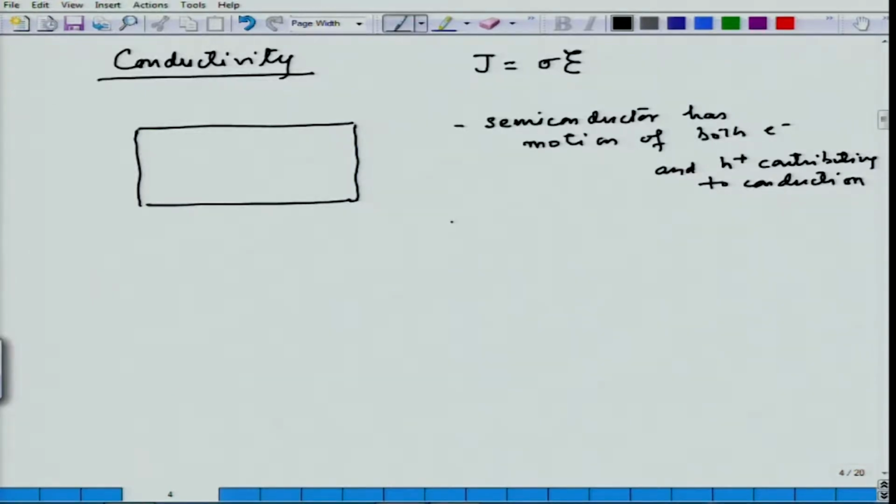And I am going to treat these electrons and holes as classical particles, as we did earlier. The only difference being the electron mass in the conduction band is going to be the effective mass of electrons in the conduction band, and the hole mass is going to be the effective mass of holes in the valence band. So, this is what I have taken from my quantum mechanical picture. I have changed the effective mass, otherwise I am going to assume the similar picture that we had earlier.